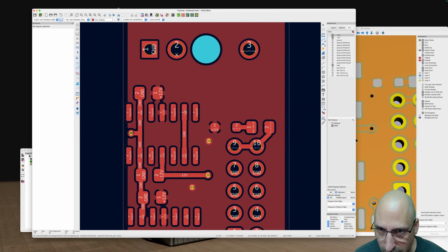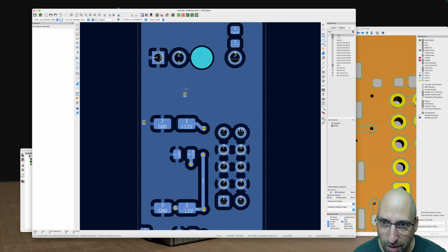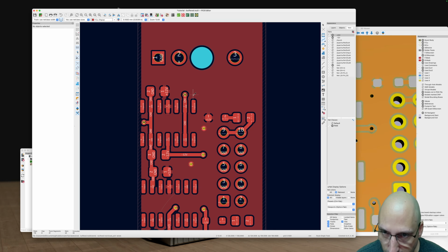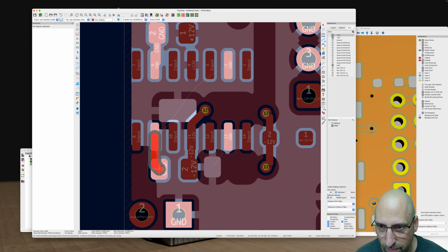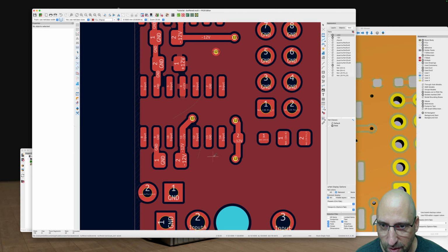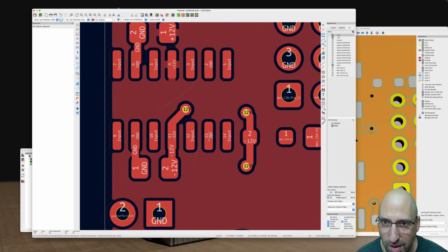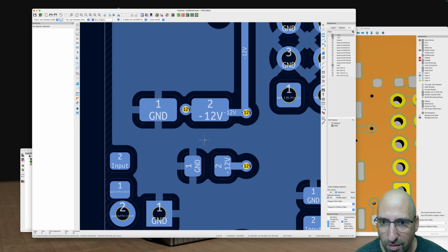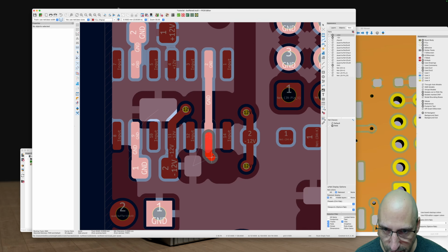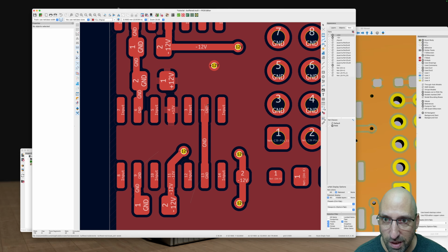I could just drop a via over here. And now we're connected to ground. So that's a lonesome pin connected up to the other ground. Have a look on the bottom. Drop a via. Oh, there's pads there again. Let's try up this way.